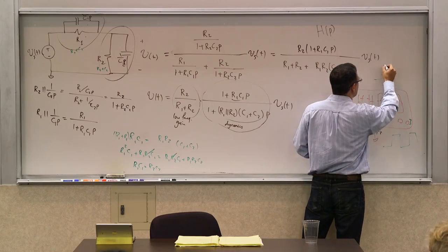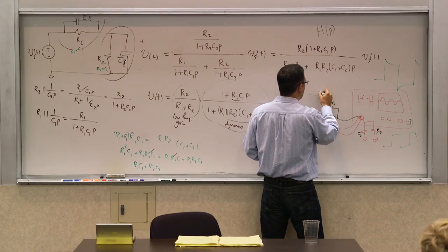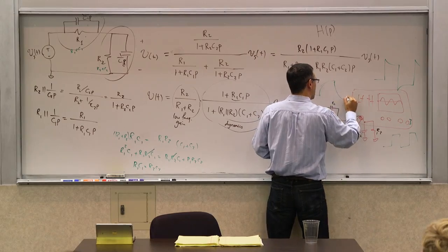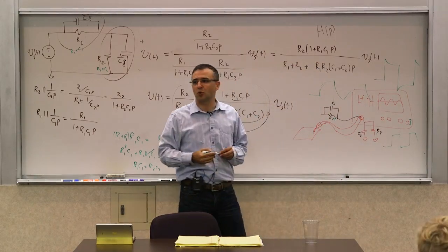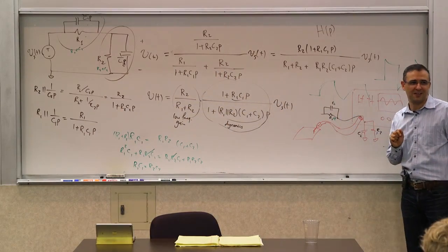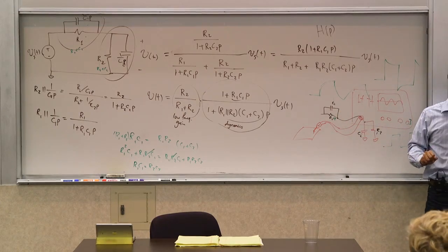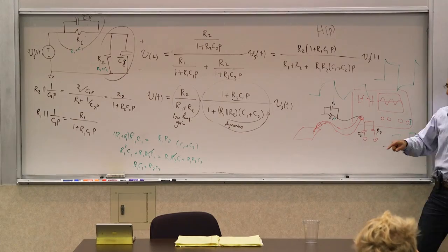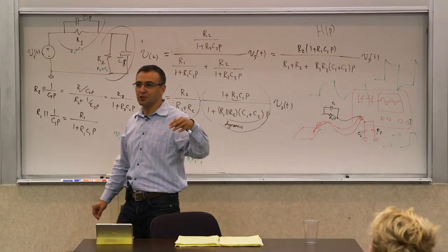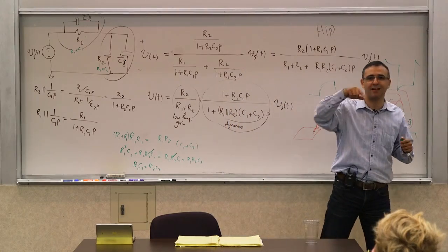Now, sometimes when you hook it up, you see something like this. Sometimes when you hook it up, you see something like this. It means that the probe is not calibrated. You play with that knob till you get this square wave. And that means that at that point, this product has become equal to that product. And that's why your probe has a 10x, because you can see it's a 1 to 10 division. So all it does is just an attenuation of the voltage, but it's the better quality voltage, so you can always amplify it inside and make it look good, but you get the correct waveform.